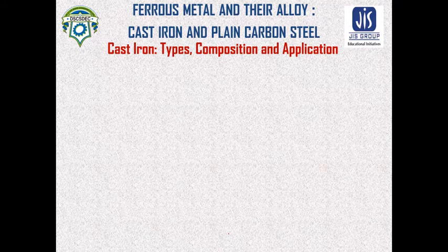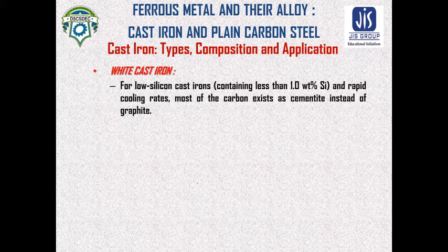Now we are coming to white cast iron. In white cast iron, which is low silicon cast iron, containing less than 1% silicon, and with a rapid cooling rate, most of the carbon exists as cementite instead of graphite.